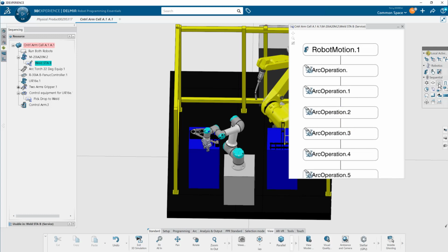So the first thing I want the FANUC to do is wait. So I'm going to input a wait statement, and the condition that it's waiting for is I_in equals true. So I_in equals true is my wait statement.